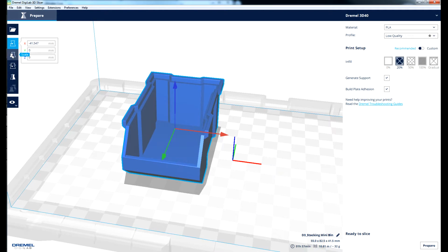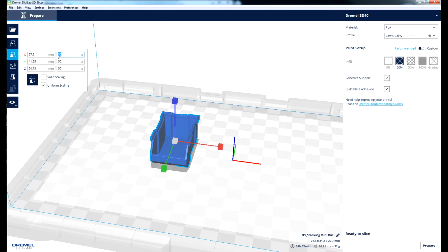When using .stl files deriving from various CAD programs, the slicer software may not be able to recognize the associated units of the model, like inches versus millimeters. You can scale your model to quickly fix this problem. This issue typically does not occur with .3mf files.